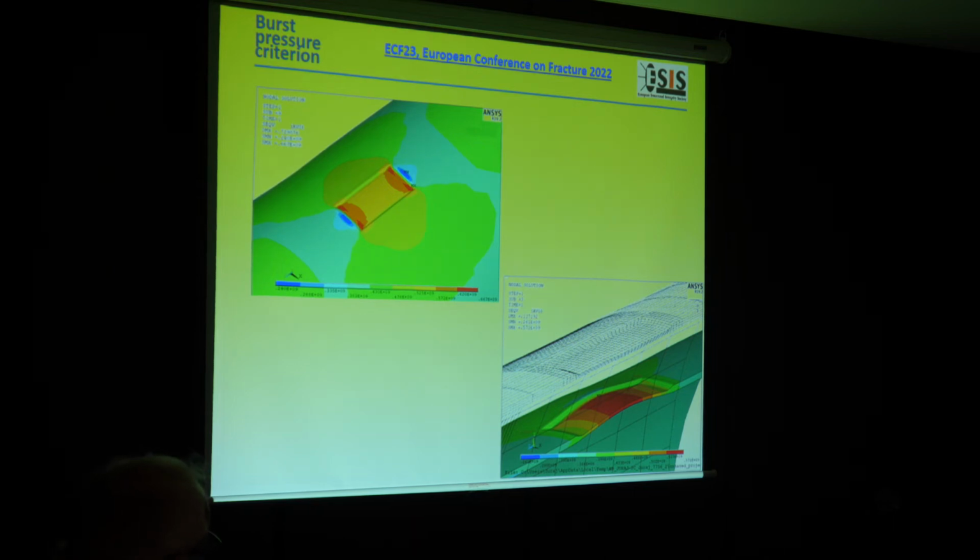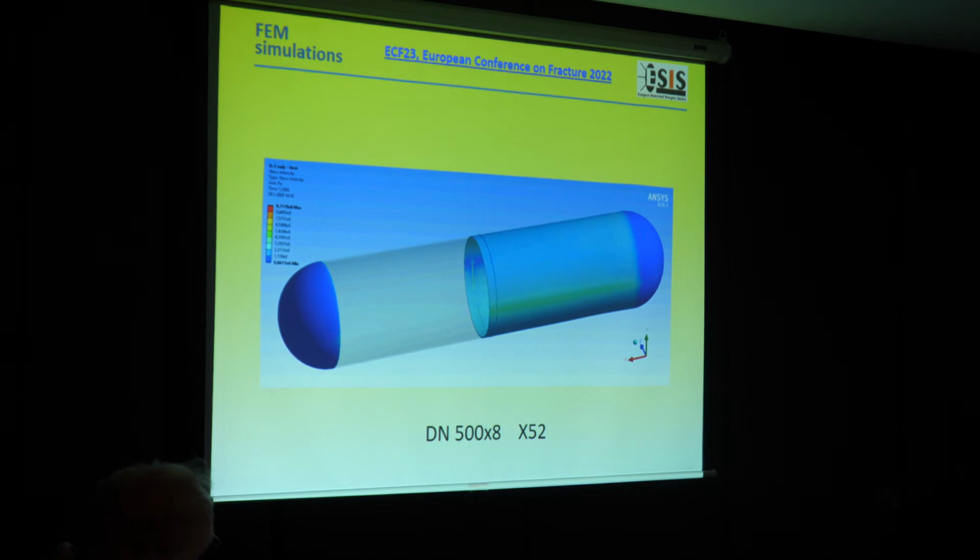It also depends on the dimension of these corrosion defects. This is a relatively very large question. It's not the time to comment on it deeply here. Here is an example of a simulation, elastic state. Now we start the plastic state. Here is the corrosion defect, not a corrosion defect but a weld defect, and it overcomes the ultimate stress, and around this is also plastic state. This is the burst pressure.